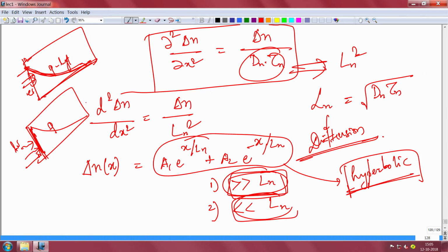Okay. So, that is one thing. You might shine light everywhere uniformly. If you shine light everywhere uniformly, then carriers will be generated everywhere, and nothing will diffuse, because everywhere the concentration will be the same. Remember, in this case there is no field, it is only the diffusion of excess carriers that is happening.